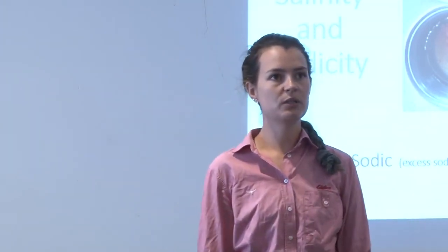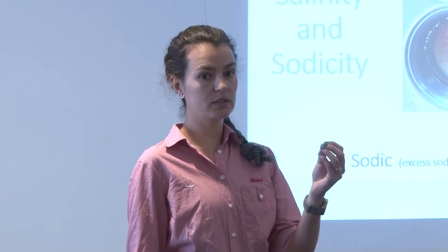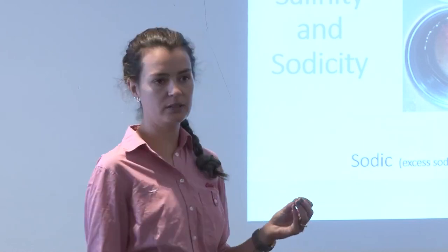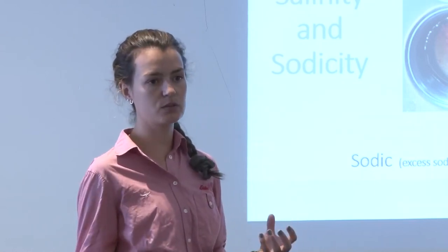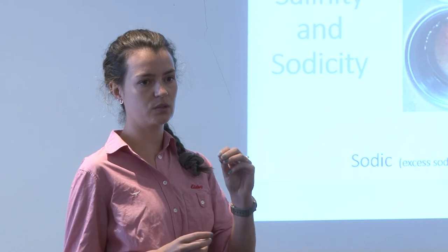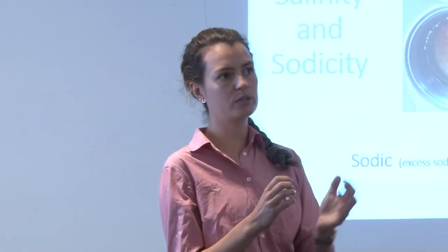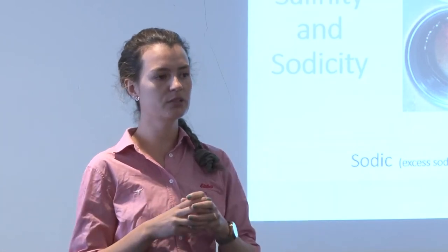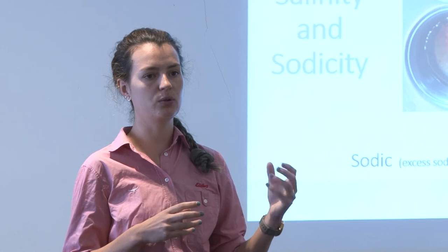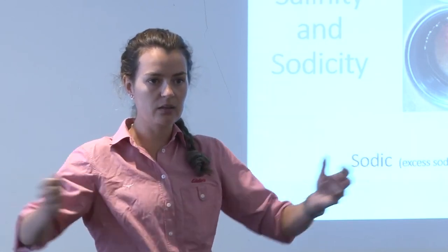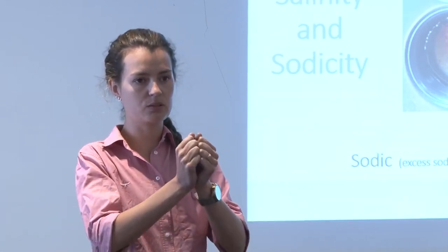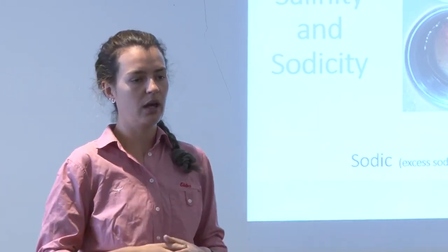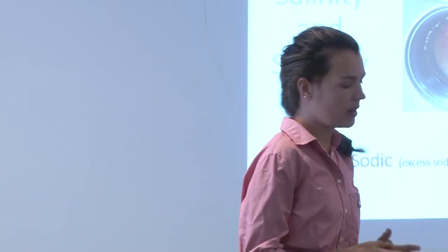So essentially what's happening, the cause is sodium, which is one particular salt. It can actually bind to what I was calling the CEC of the soil. So it's taking a position on the soil, and when water is introduced, each sodium particle on each different site of the clay or organic matter is repelling one another. Sodium doesn't want to be close to one another, so it's repelling and it's becoming suspended in solution then. So that's what's happening there.